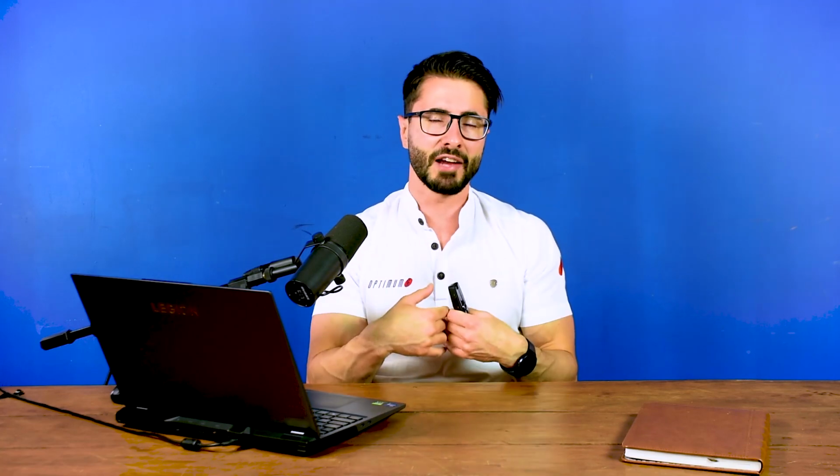After that, a very good way for you to quantify the influence of damper on vehicle grip and stability is speaking with your driver. Depending on how you change the damper characteristics, and we discussed this in another question, you will change the transient load transfer distribution of your car. So you could be increasing the vehicle's response or actually decreasing it if you're getting too much rotation. And the driver will be a very good source of information for that type of behavior. Besides that, you could be working with KPIs, so key performance indicators, using the data to quantify the changes.